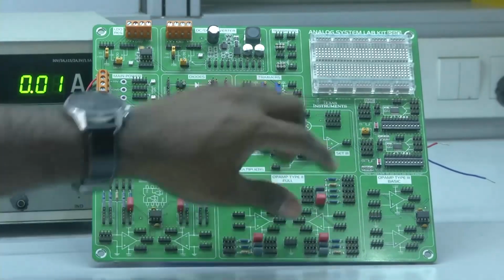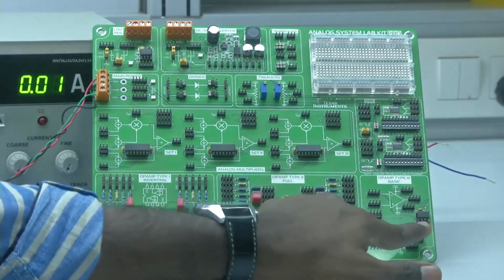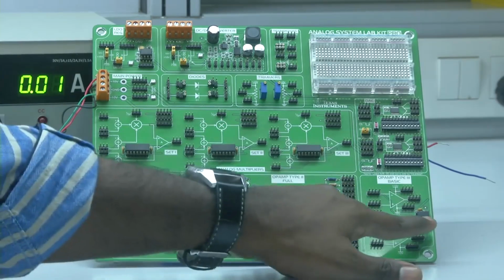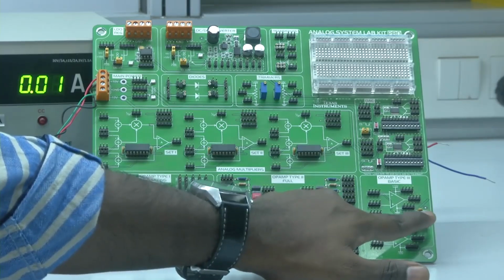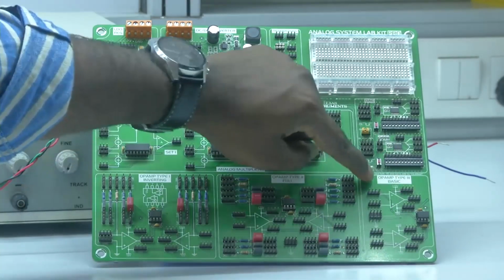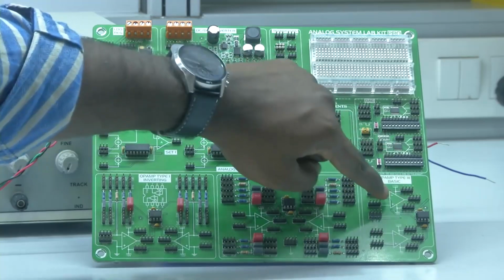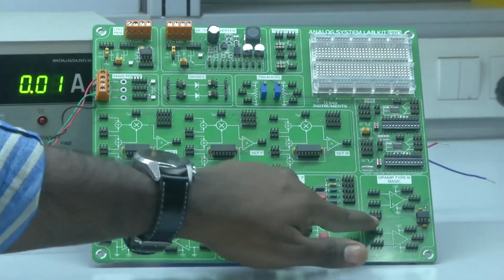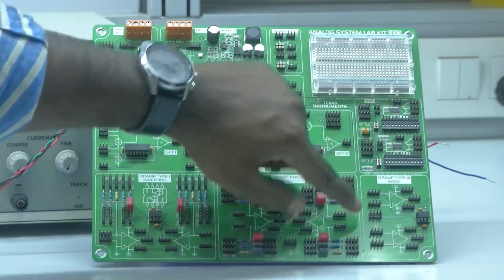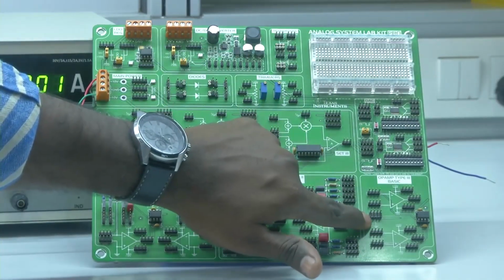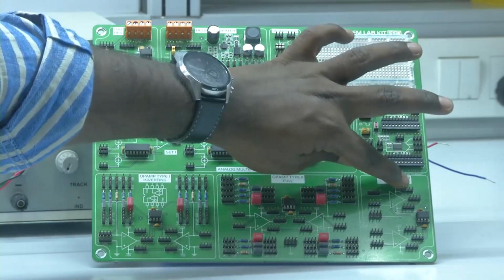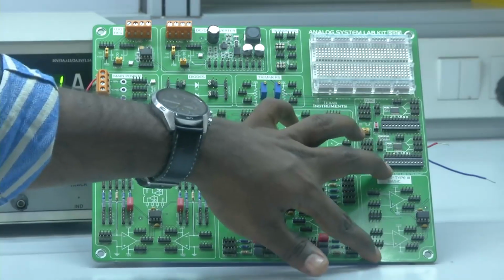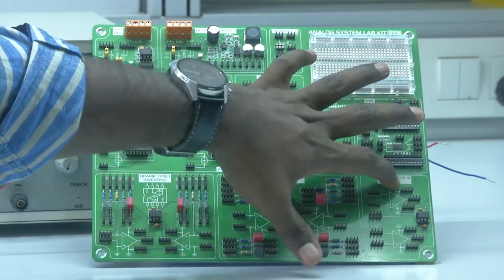If you carefully look, this is the IC, which is a TL072, a dual op-amp. Since it is very difficult to understand the configurations directly, the negative terminal has been connected with 4 mm banana connectors, and the positive, non-inverting terminal has also been provided with banana connectors, and it also has separate pins for the ground and a 10 volt power supply. If we want to provide a single power supply to the board, this particular subsystem can do that.